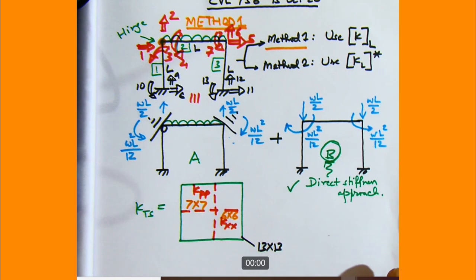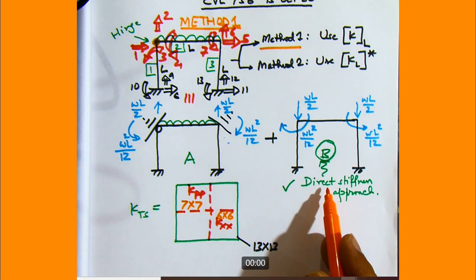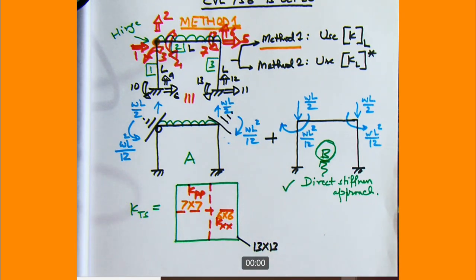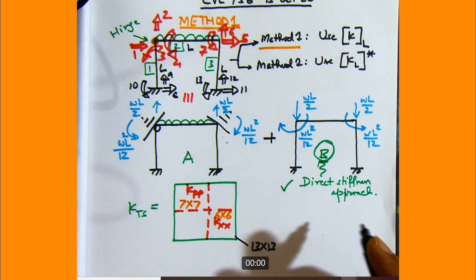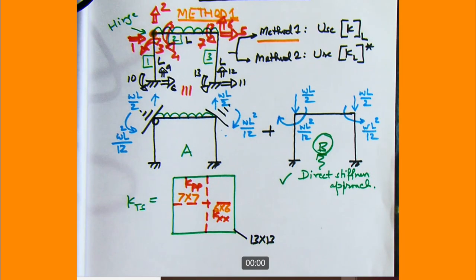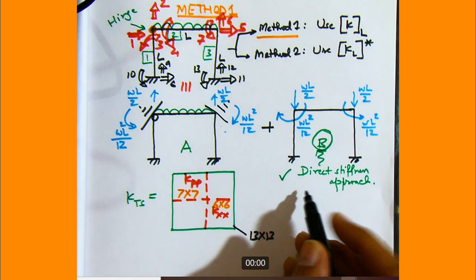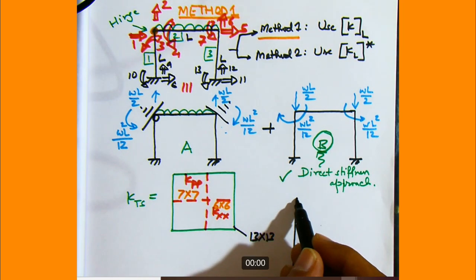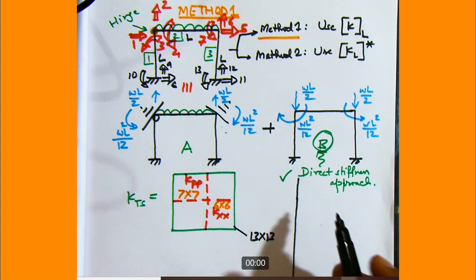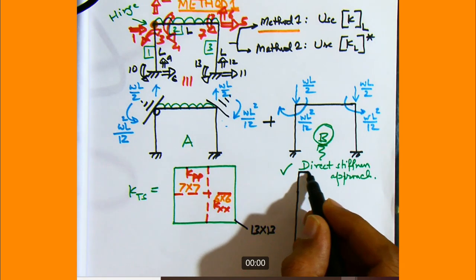Next step is that we have to form the load vector or the force vector corresponding to structure B. So force vector will have now 13 terms. So let's make a matrix, and then we'll keep on filling the values for this. And I just draw a shorter one so that all 13 can be included here. So this is our force vector consisting of the two components. One component is P and other is X.